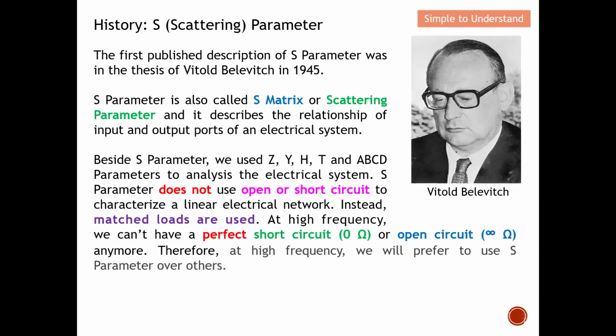The key reason why we want to use S parameters is because S parameters do not use open or short circuits. Z and Y parameters use open and short circuits, but for S parameters we don't use them in order to characterize a linear electrical network. Instead of open and short circuits, a matched load, let's say 50 ohm, is typically used.